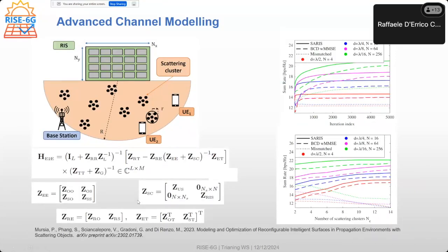I would just want to say that the scattering model, the impedance model, was extended to this kind of rich scattering environment by representing the scatterers as a bunch of dipoles. By knowing this channel and modeling the multi-parameter, it was proven, and will be shown later in another presentation, that this could be helpful to optimize the communication.